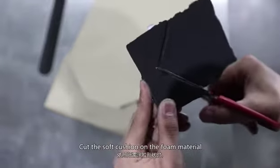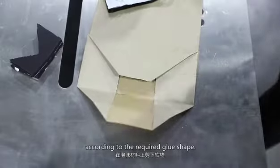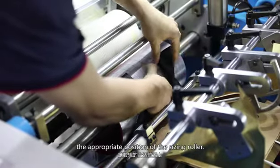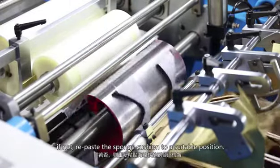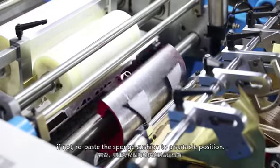Install the soft cushion on the bottom-coated side of the bag. Cut the soft cushion from the foam material according to the required groove shape. Paste the foam cushion at the appropriate position of the sizing roller. Rotate the machine to check whether the grooving is normal. If not, repaste the sponge cushion to a suitable position.